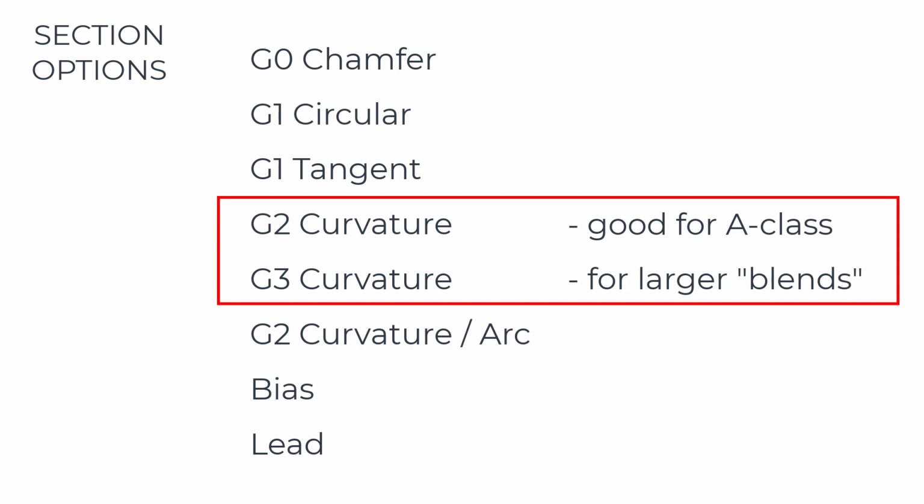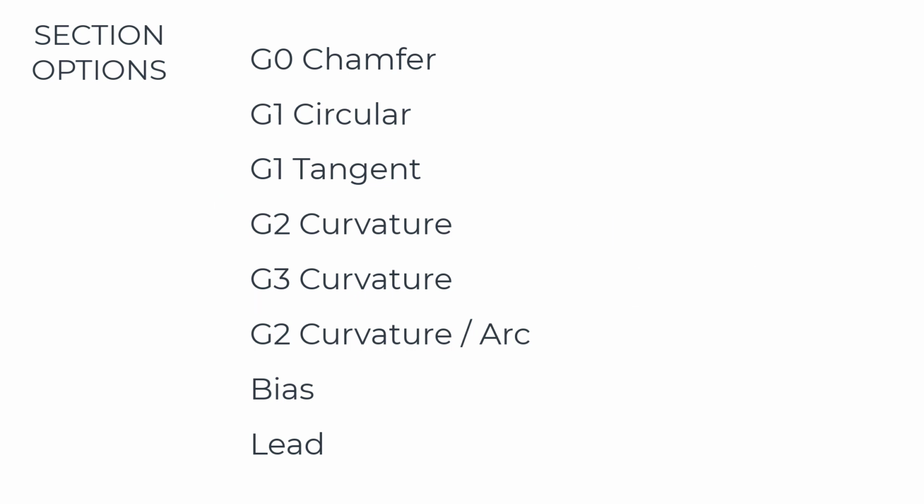Personally, I nearly always use G2 fillets with a form factor of 1. Being the default, it's easy to remember. There are arguments for using form factors other than 1, which is fine, but it's one more thing that we have to make sure we get right every time. I might use G3 if the fillet's very large, where it's more of a blend than a fillet, for instance to define the corners of a bumper. Otherwise it's always G2.